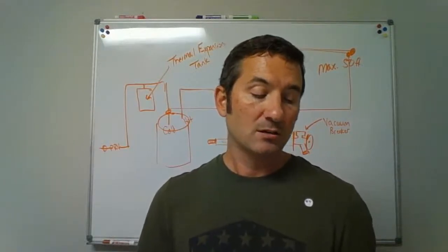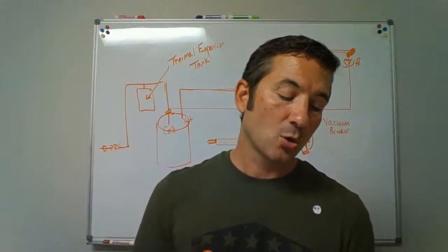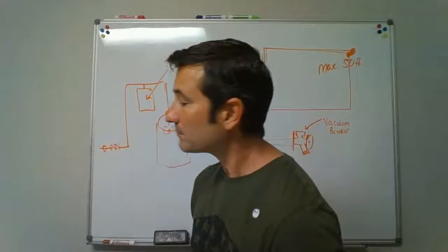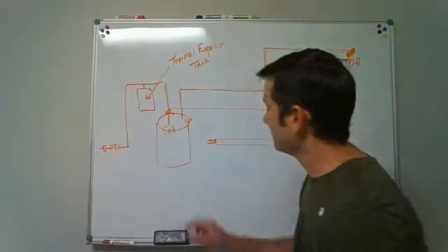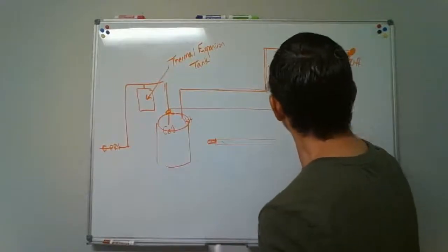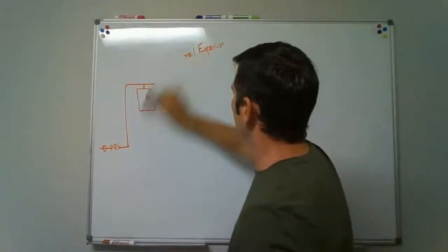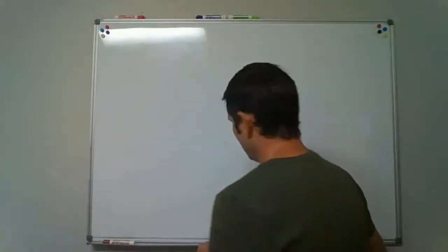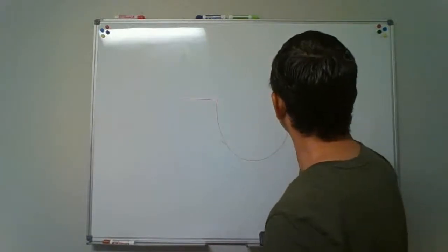Question 14. How you measure the air gap is from the lowest end of the potable water outlet to the flood level rim. How you're measuring air gap as it relates to the water supply and distribution system here.